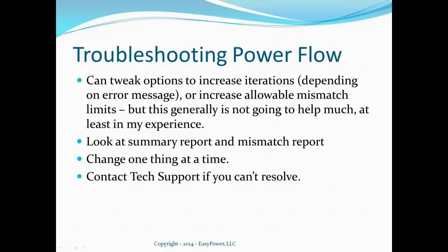Question: don't most cogen models generate enough power and use import-export kVA to control load on the generator? Not quite sure I understand the question. Most people with cogen systems want to produce as much kW as possible. They don't want the kW to change because that's how they make their money. They want the utility to make up the difference.